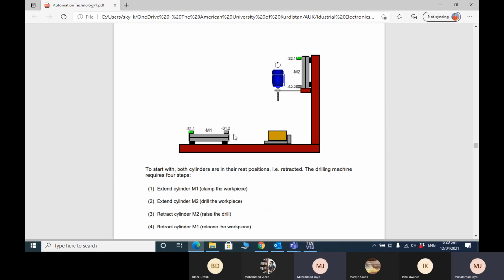In the relay logic control, if you remember, if you wanted to use this sensor multiple times, you had to use a switch of a relay. Here you don't have to do that, because this is an input, and the input can be directly connected in the PLC.